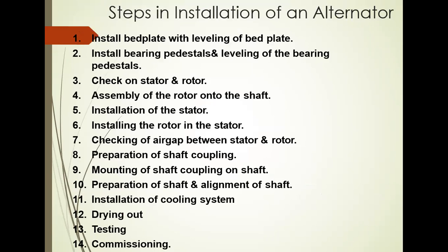Then what are the steps needed for installation of alternator? First, initially the bed plate, that in the previous slide the blue color denotes the bed plate, right? So first install the bed plate with leveling of bed plate. The leveling also is to be considered.